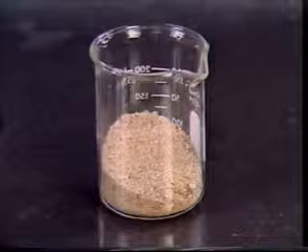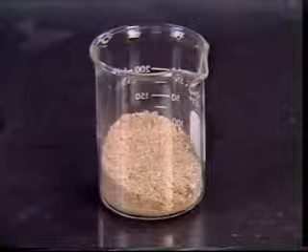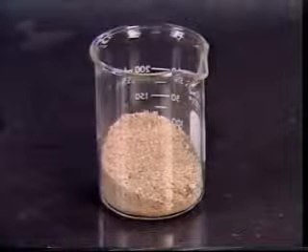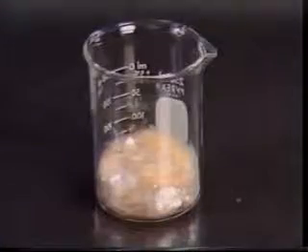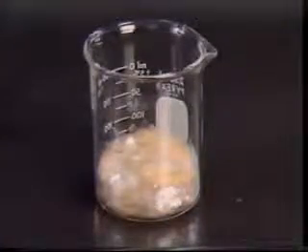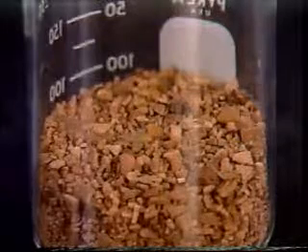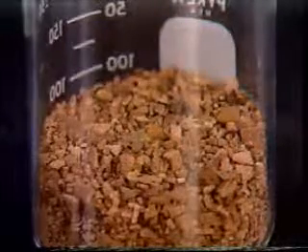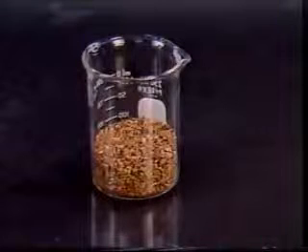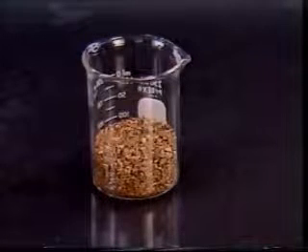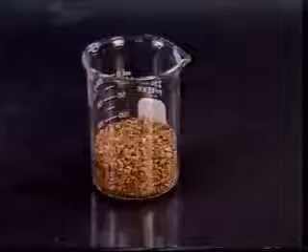Such materials are categorized as fibrous, including paper pulp and wood or vegetable fibers, flake, including shredded cellophane and mica, or granular, such as ground nut hulls, calcium carbonate, or even used automobile tires. Once the material has successfully plugged the void, remaining material is removed from the mud system.